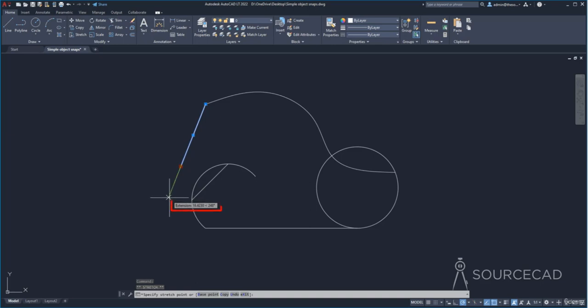Now, as long as you have this extension option on the tooltip, you can be assured that it is extending exactly along this direction. If, however, you move it further away from that line, that extension option will disappear, and now it's not following that line. So move it close to this line, and here we are still extending it again. That's the extension. You can do the same for arc. So go to arc and extend it right along this direction. Again, if you move it further away from that point, it's not going to extend it, and it will just be a simple drawing. So just move it closer, and once again, we are extending it. You can move it all the way up to this point. When intersection shows up, click, and that's the extension tool.